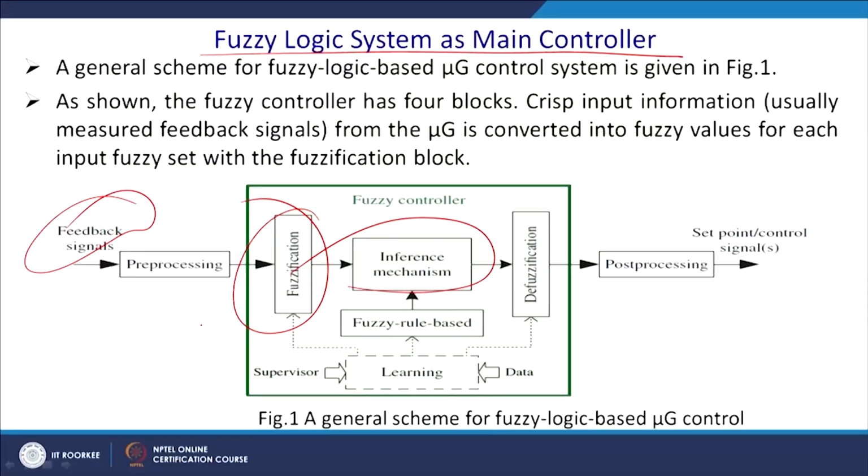and this is basically the supervisor and this is the data, and thus you have a rule base, and this rule base is formed from fuzzification. You have an inference mechanism, and this is a fuzzy rule base. Then you will have to defuzzify, and there is a method called the centroid method and other methods. You will calculate the area. Ultimately it has to find out what should be the value of Kp. You have so many inputs, so what should be the value of Kp and Ki, or in case of the washing machine, what will be the timing. That is the defuzzification.